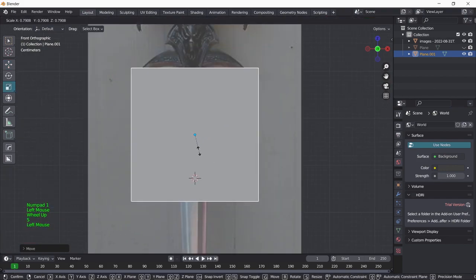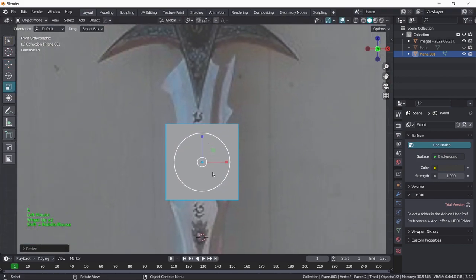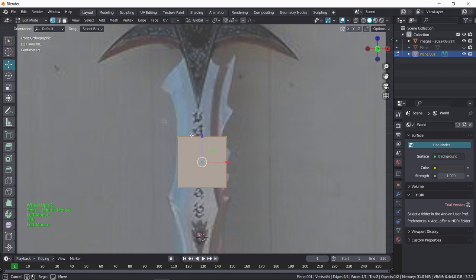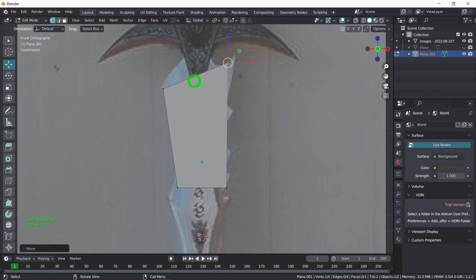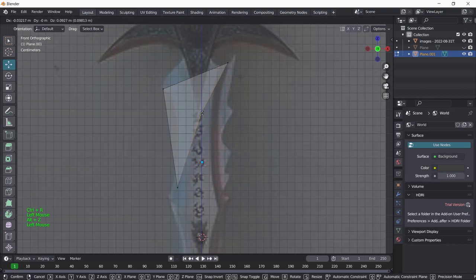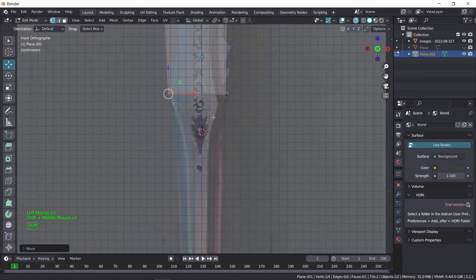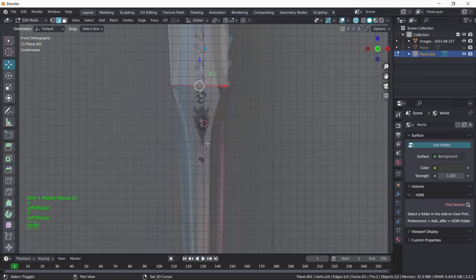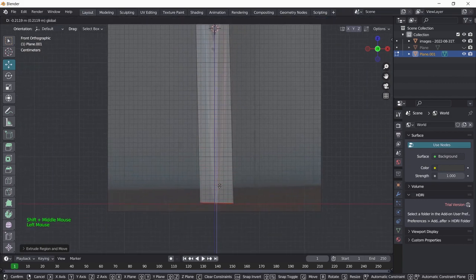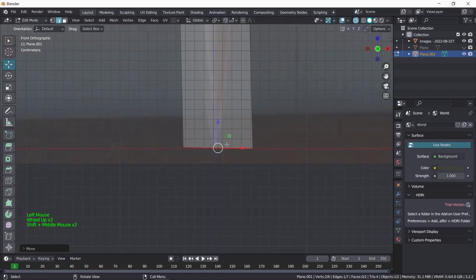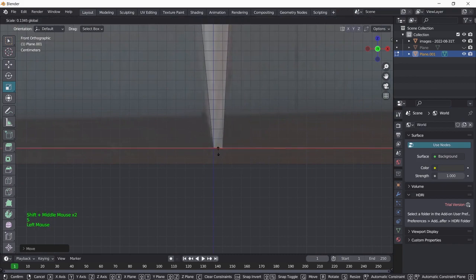And if we just set it up so that we can make the basic shape of our knife. So let's just go ahead and mark it like here and here, the two major points. Grab this and just press W to extrude it down and just bring it down here. Press S, you can bring these in.